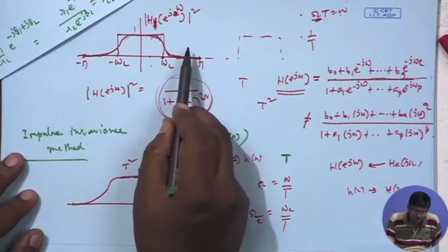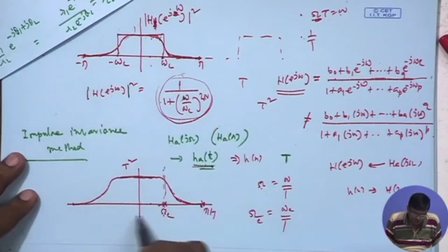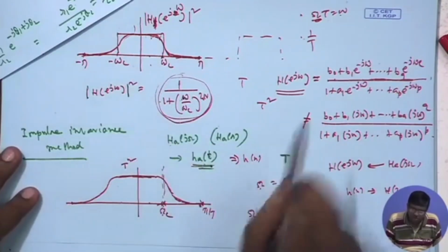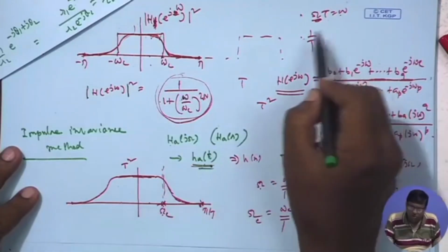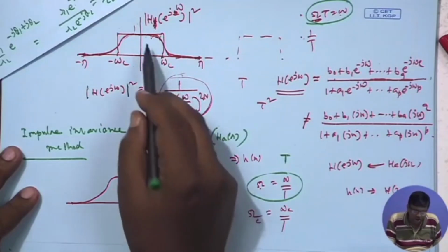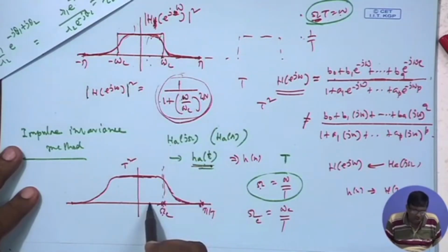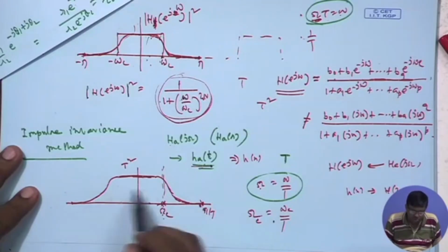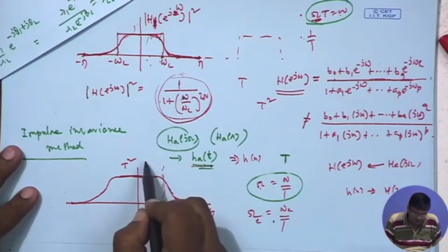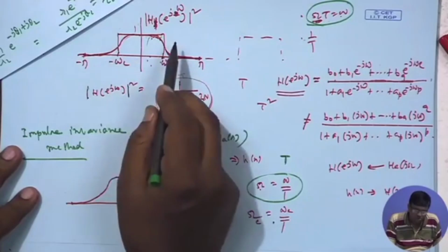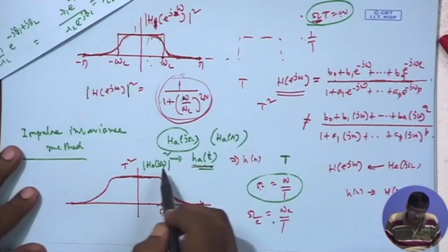Now, if it is Butterworth, when I go for constructing that analog low pass filter, first I will do these things. This will be the frequency transformation. At any small omega, whatever value we had here, that will go to the corresponding capital omega by this relation. So, omega c will become capital omega c like this, pi will become pi by t, and so forth. So, I construct this function, giving this frequency response, magnitude response, I construct one analog magnitude response in this way.